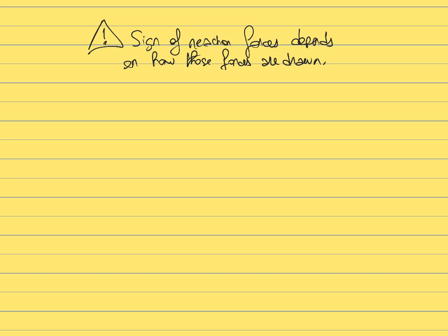The other thing to keep in mind is that since the result that you get depends on how you draw them, you need to make sure that you draw those forces and that you are consistent between how you draw them and the projection that you write in the condition of equilibrium. But again, keep in mind that the true reaction from a support, physically speaking, is always going to be pointing in one given direction, independently of how you draw it, because that's just the physical reality: if you push the material in one direction, the support is going to oppose this material.